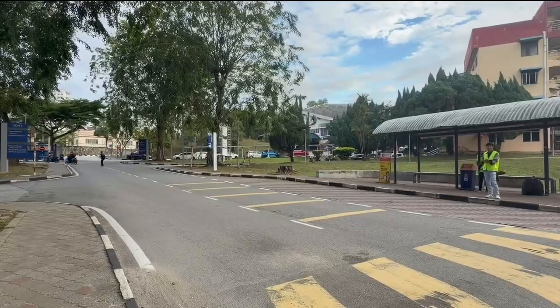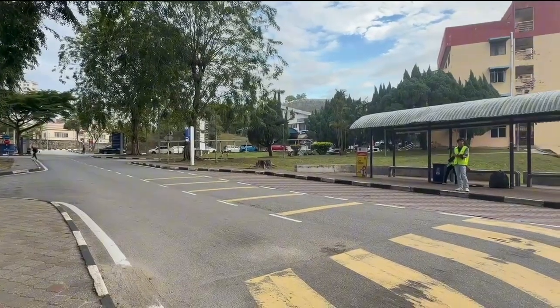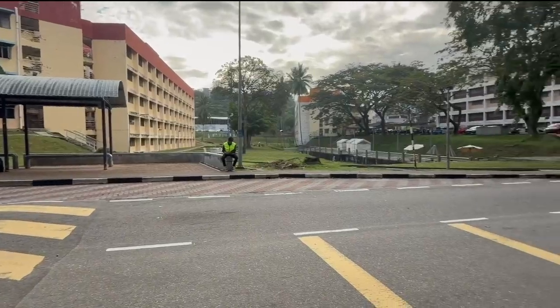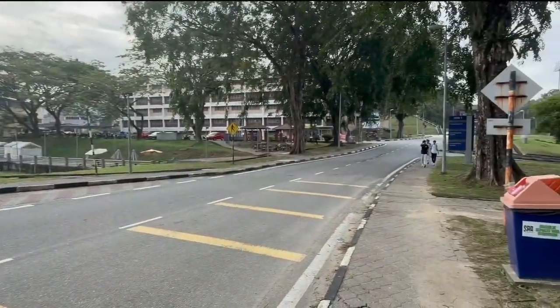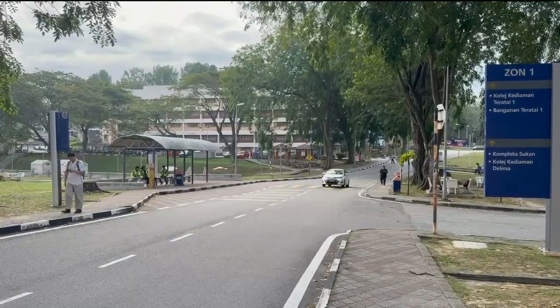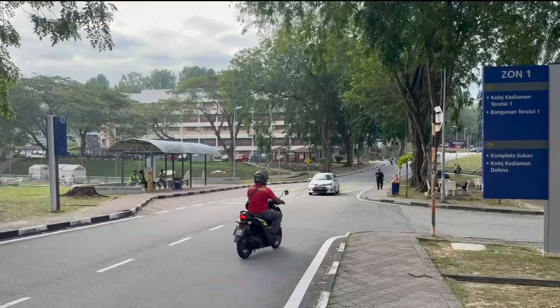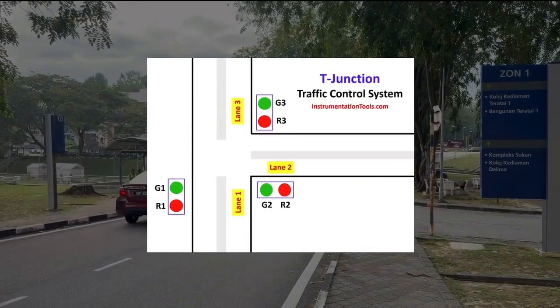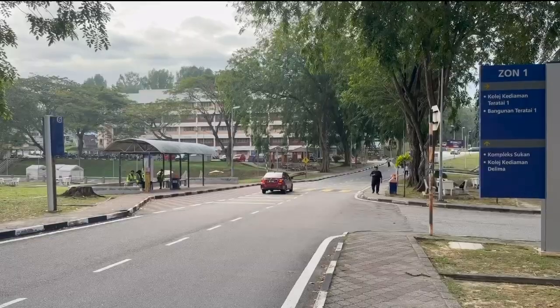The location, spacing and visibility of signal faces must be carefully planned to operate effectively for all road users. Adequate signal hardware with redundancy should be installed to maintain reliable operation. Pedestrian signal provision should be included, especially in built-up areas, to ensure safe crossings. Proper signal timing and coordination will help manage traffic flow, reduce delays and minimize the risk of accidents.